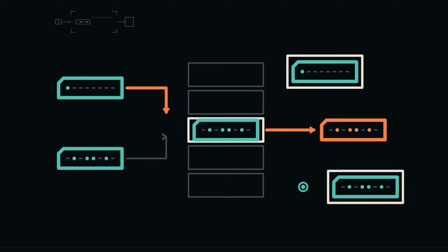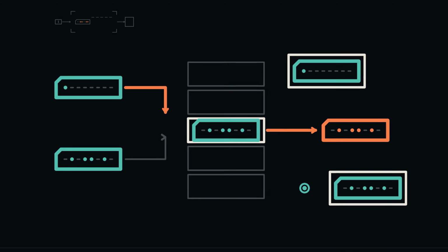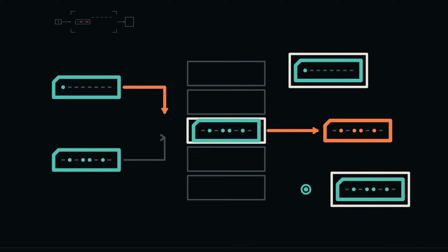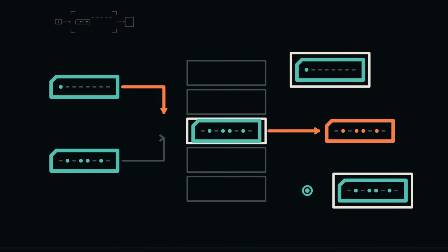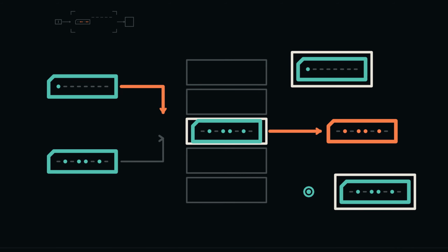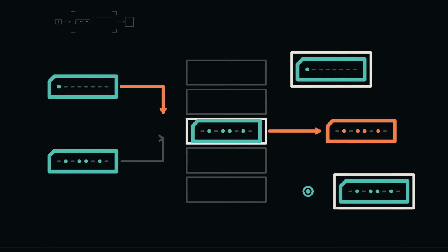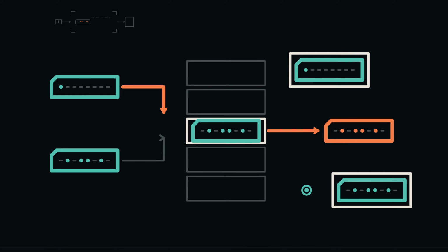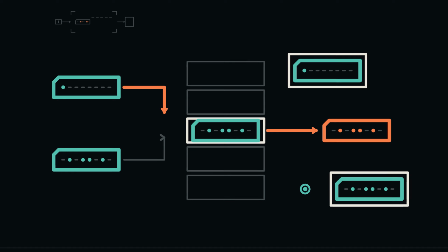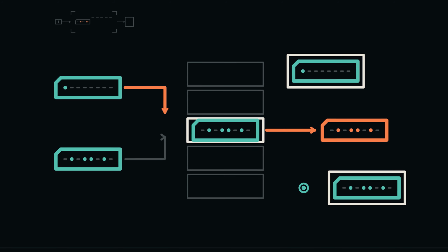The memory row remains 5A, reading has not consumed or cleared it. The trace marks this memory event committed because the read value has been captured at the module boundary, not because memory content changed. The returned byte is now stable in MDR, but the requesting register has not yet received it. In a final consume action, MDR drives the bus and the destination register captures at an edge.